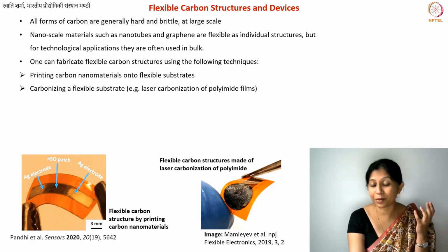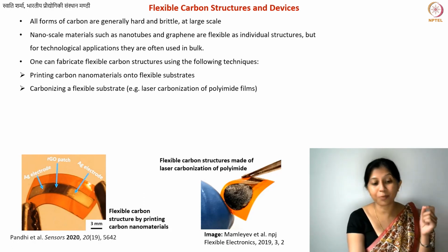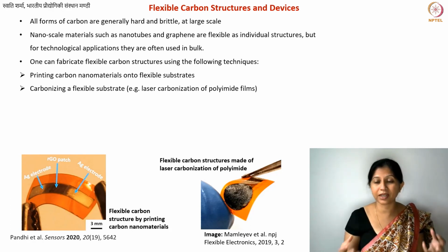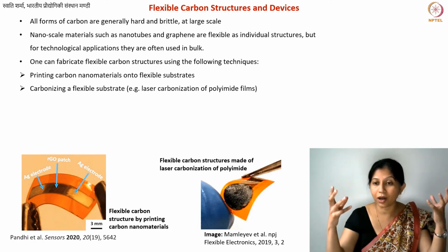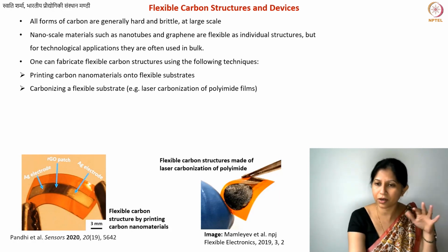However, the property of carbon, the quality of carbon is not going to be as good as any of the large scale carbon materials, even if you induce very high temperatures. The reason is that the process is happening extremely fast. So it is not like when you keep something inside the furnace, then you anneal it at very slow ramp rates, so 5 degrees centigrade per minute, or even slower than that.